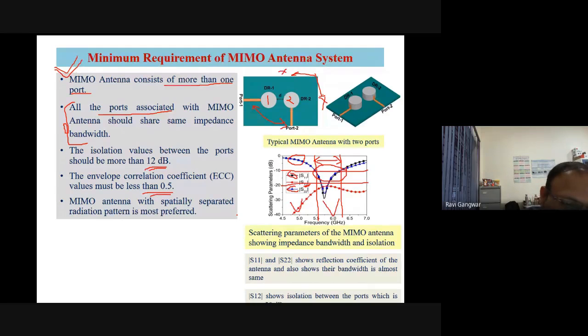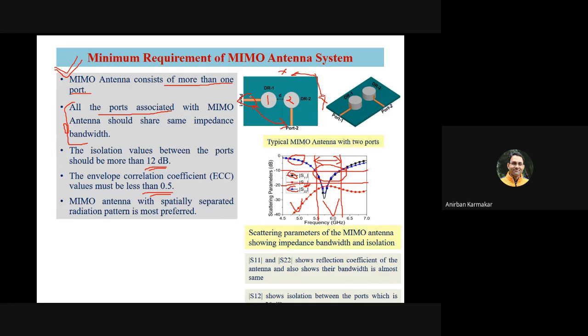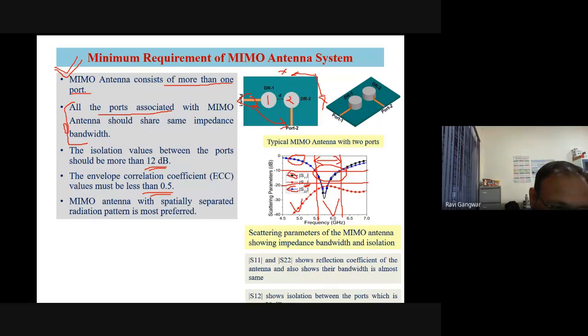It means the feed lines which are used to feed your antenna are also participating in the radiation. In that condition, port-to-port isolation analysis is a requirement that you have to do. That analysis is required. Otherwise, you cannot get a better result. So that's why I consider both things, port to port analysis along with the far field. So our ECC value depends on both parameters.